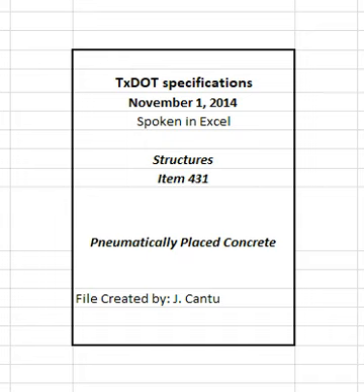Pre-bend the welded wire fabric for encasement of steel members using a template to conform as nearly as possible to the outlines of the members to be encased. Drill holes between 1/2 and 1 inches in diameter in the webs of the members as close as possible to the flanges to allow for attachment of the reinforcing fabric. Space these holes at approximately 3 feet on center.